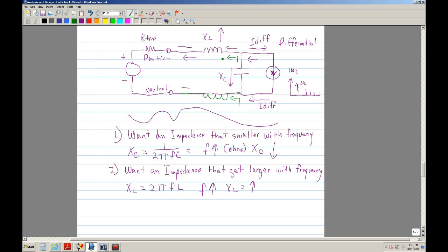One of the reasons is that when it comes to common mode, if you have an unbalanced positive and neutral, common mode can be converted into a differential mode. If you use a balanced input filter, it prevents the common mode from being converted into a differential mode. But basically that's what they do. And another thing they do is couple these inductors.